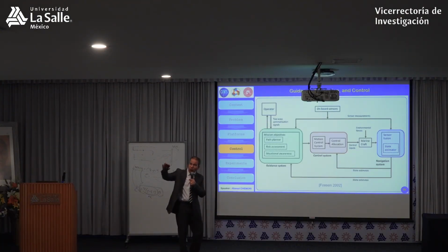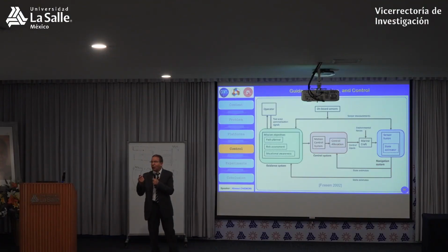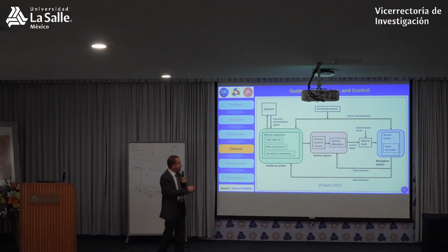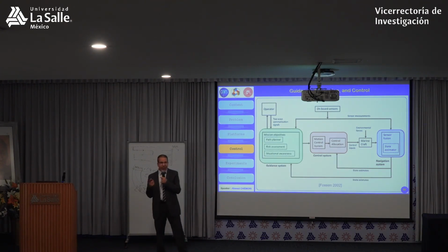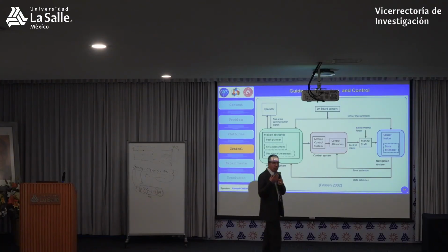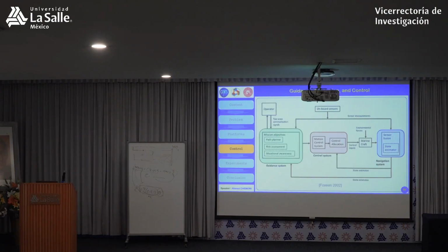However, sometimes you have to follow a predefined trajectory, so the reference should be something which will be time varying. How we generate what we desire as a reference is in this block, and this block is called the guidance system. So a guidance system in an underwater vehicle is a block that generates the reference trajectories for your vehicle depending on the task. I want to follow a predefined trajectory, I want to stay in a specific position, what I want to do exactly. Then this block of guidance will generate the reference trajectory that goes to the controller.